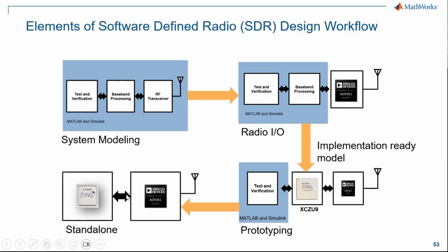And then the next step is the ability to take your model. So there is a workflow where we go from MATLAB to Simulink, and we make our Simulink model what we call hardware friendly. So we make it using fixed point rather than floating point, so that we can take advantage of CPUs or the FPGA, and in general it's both.